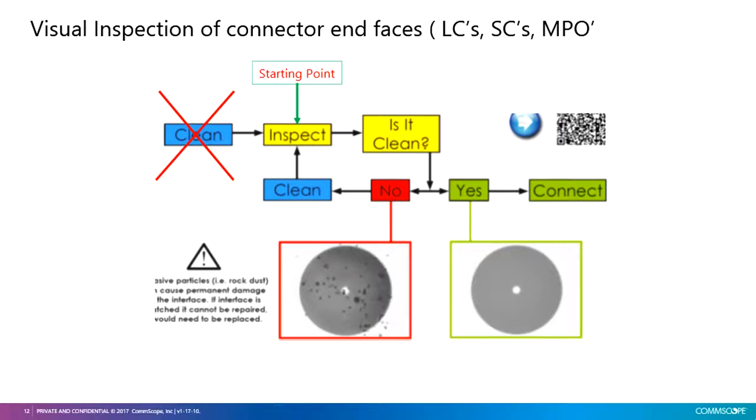I want everyone to remember the starting point. First, we need to inspect the connector before cleaning. Cleaning blindly also adds some losses to our link, so we need to be extremely careful. First, we should inspect the connectors.